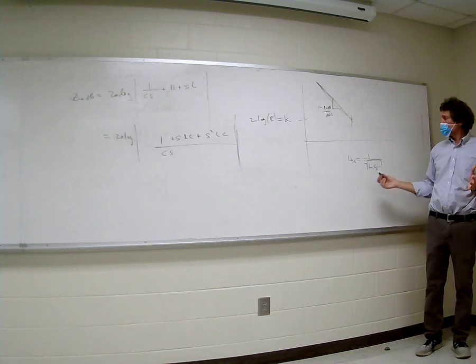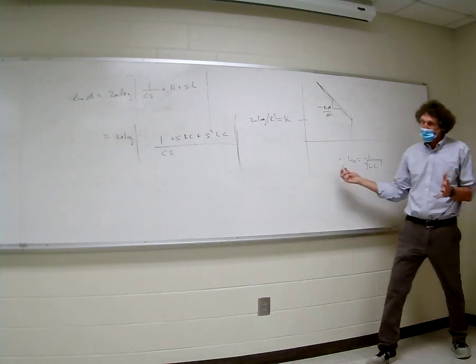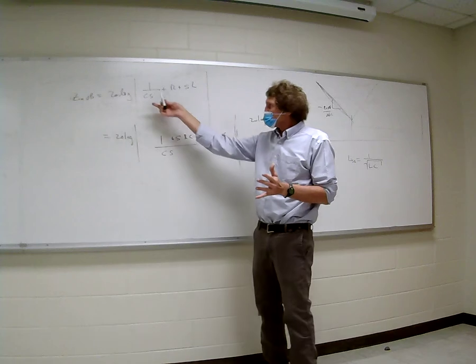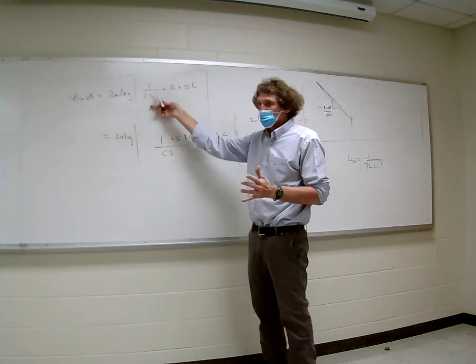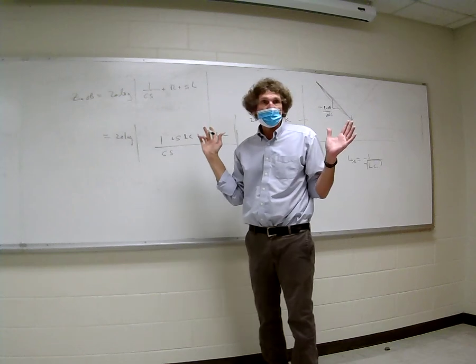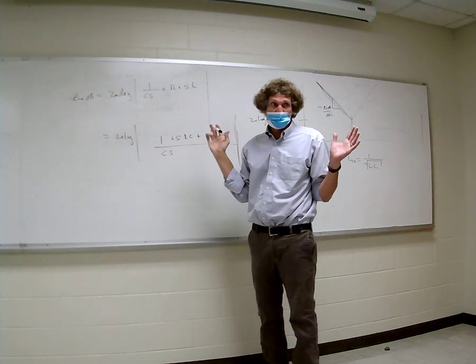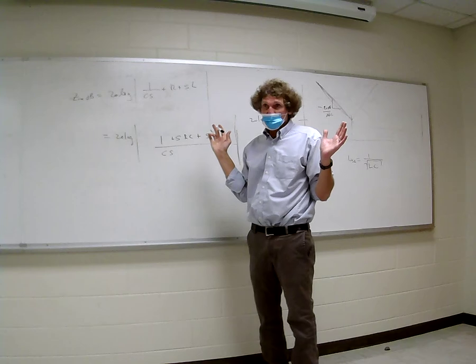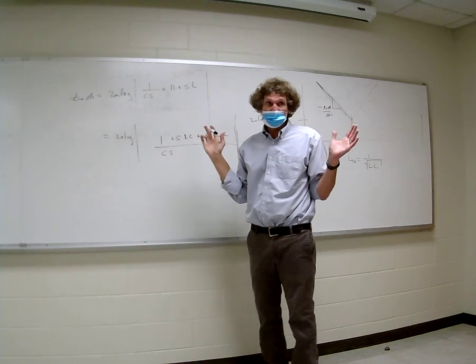Remember this one thing, the key to this is understanding that when you're at resonance, the capacitive reactance is equal to the inductive reactance. They cancel. If it was in parallel, all right, they would still cancel. You understand? With me on that?